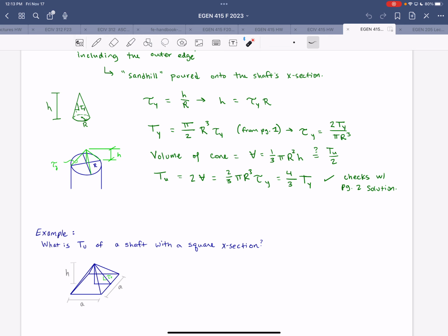I wanted to make sure that nobody was trying to go overboard with the rectangular cross section and get an exact stress result from a rectangular pressure vessel, because that is more complicated. You have to think about stress concentrations, and that's not the intent of this problem. So just simplify it.